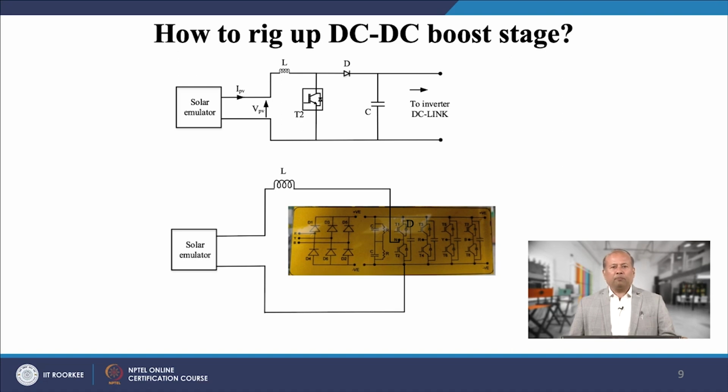We can connect the positive terminal of the PV input to an external high frequency inductor whose other end is connected to the point N. The lower side IGBT T2 can be used as the switch, which is connected between point N and DC bus negative.